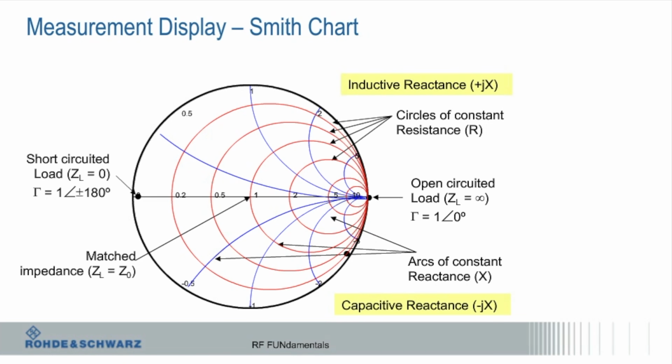First off, it has some electrical length associated with it, right? That length is a function of frequency, so as you change the frequency, that length changes. So you can actually add delay to that measurement and move it to more or less a dot. But that's the more general answer. The reality is, more so than even that, when I make any of these standards, do you think it's a perfect short from DC to 100 gigahertz? I'd be retired if I could make that, right? That's a hard thing to make.